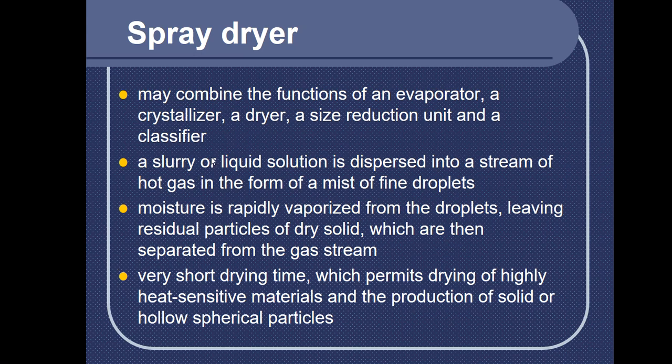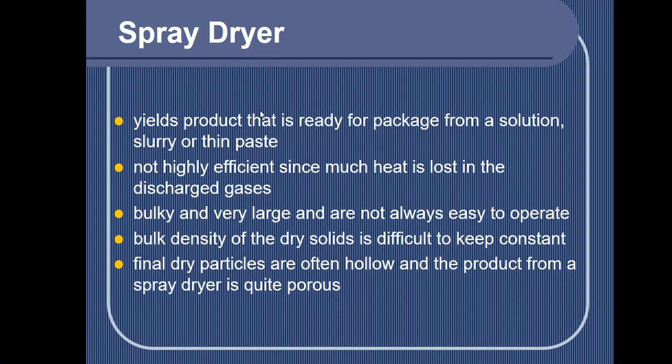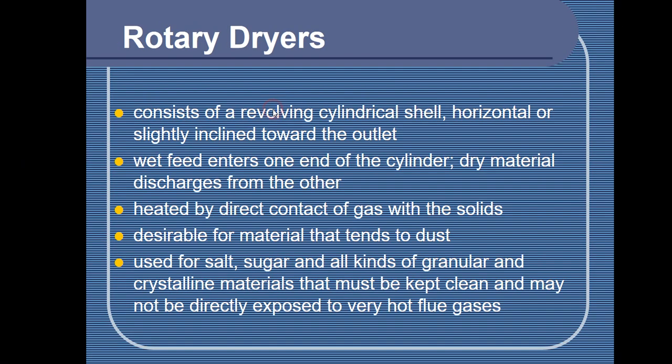As to the illustration of these specific dryers, I have included it in your heat and mass transfer slides in your course. So just refer to the specific illustrations for this. Now, very short drying time. I think this is the only dryer that mentions that the drying time is short, which permits drying of highly heat-sensitive materials and the production of solid or hollow spherical particles. So that's special about spray dryers. Now, this is more to read on the spray dryer, so please read it.